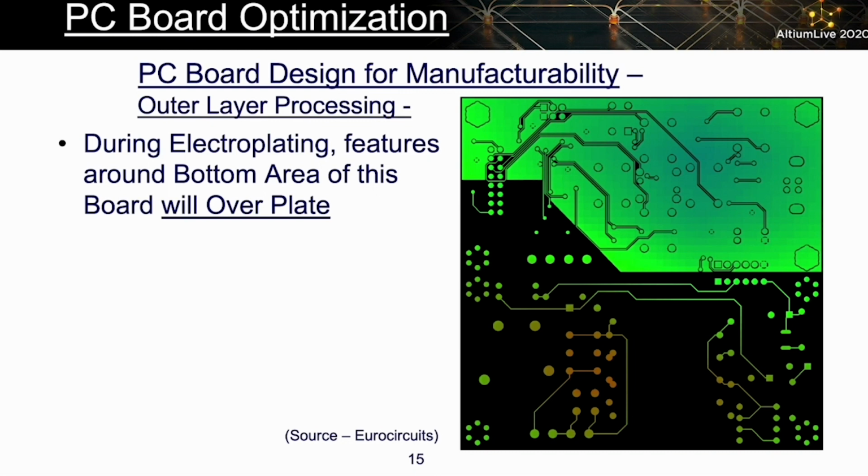And they would say, because this board has uneven copper all over it. We can't plate it evenly because you haven't distributed copper evenly. Remember, we're going to put, let's say, 6 or 8 of these into an 18 by 24 panel. Let's say we're going to put 8 of them in a panel. When they drop that panel into that plating tank we just looked at, the fields from the copper anode conducting to the panel are going to attempt to couple evenly all over this entire panel. Why? Because there's copper underneath the plating resist.